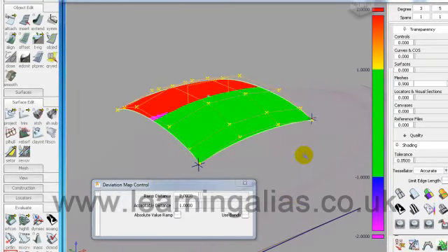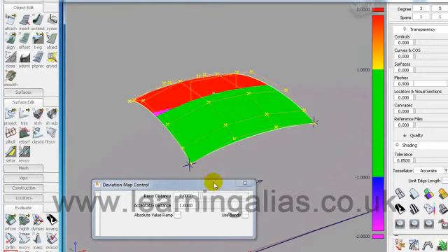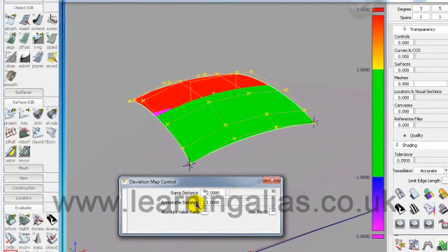Just to finish up this video tutorial, I want to show you this is the tool. The acceptable distance is 1. That's the distance you're going to be asked to work to in industry, and if you go for an interview you might be asked to surface a mesh with a tolerance of 1 mm. But I want to show you that my model is actually probably closer than that, so let's see if it is.